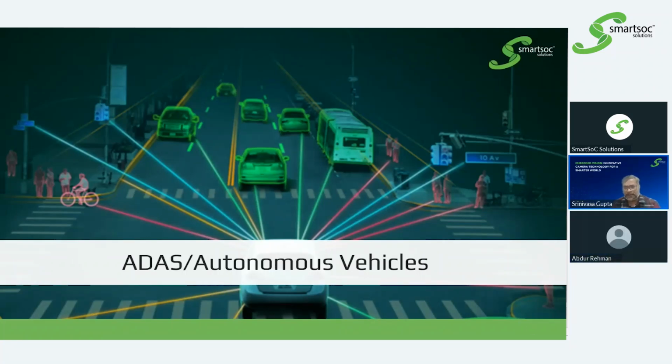So front, rear and side cameras all together, and we need to process it together, and even other sensor data also needs to be processed, like lidar and whatever you mentioned. All those sensor information needs to be processed to take a decision. So camera is the best one for capturing entire image and information. Understood. So that is what sensor fusion is. You have different sensors fused together, synchronized, and you try to take a decision, right?